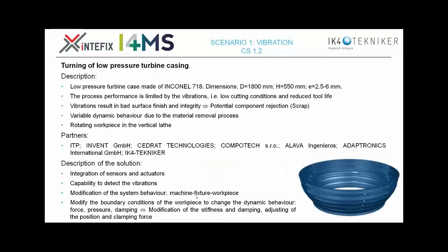Well, the second one is also related to vibrations. It's a case made of Inconel 718 for aircraft applications. As you can see here, it is a relatively big component, and also in this case there are problems associated with vibrations due to the low stiffness of the component. As you can see, the thickness of the component is really low related to the other two dimensions of the component.